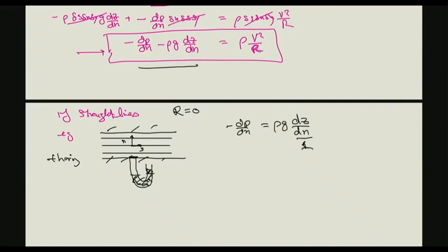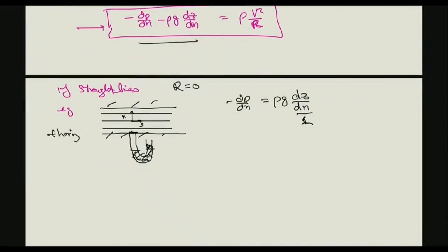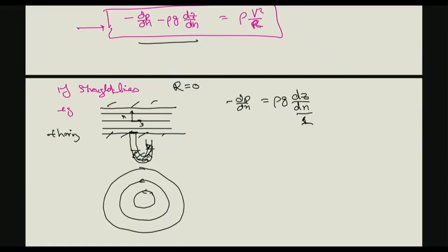The other example I want to give, because it's still maybe a little hard to envision the significance of the normal direction. Suppose you have a flow with circular streamlines, and this sort of flow might be used as a model, say, for a tornado. So like a vortex, where you have the circular motion. And then let's say this is in the horizontal.